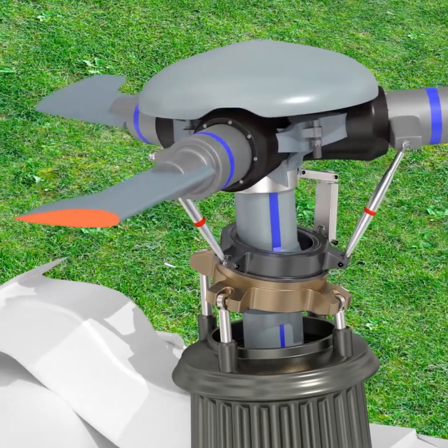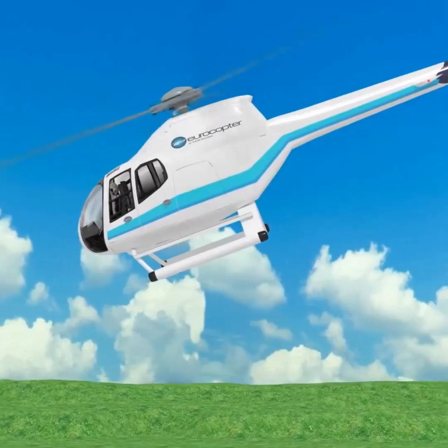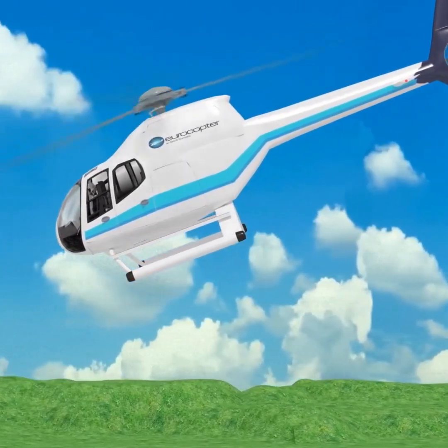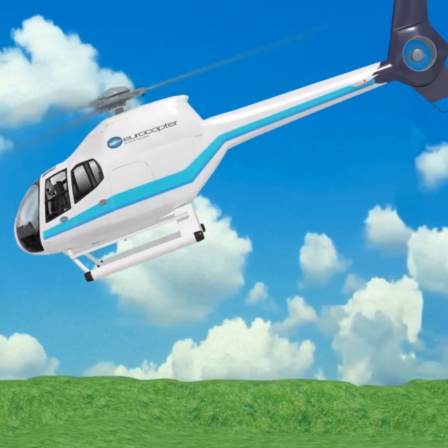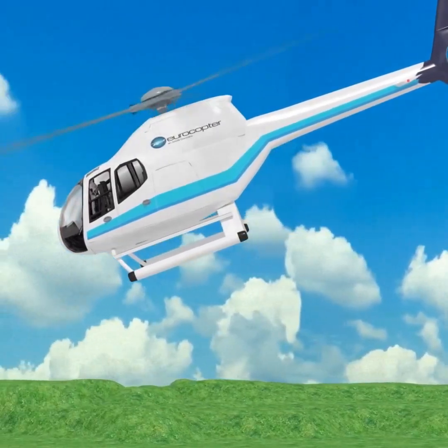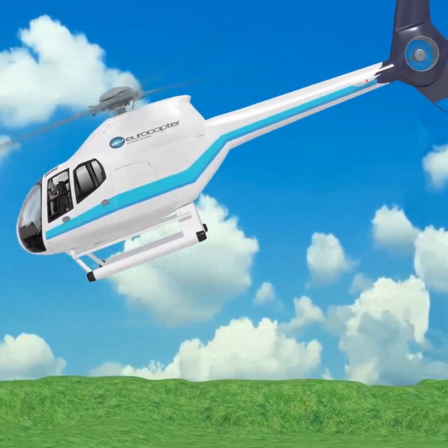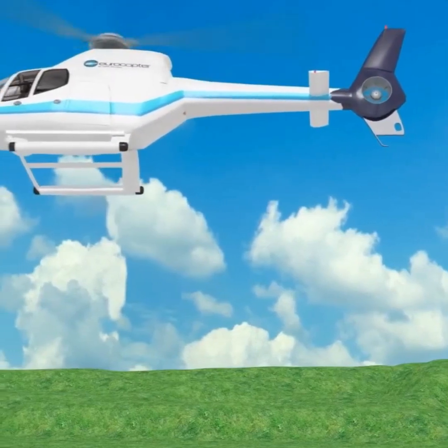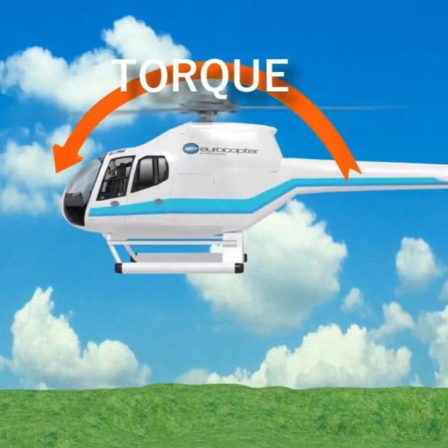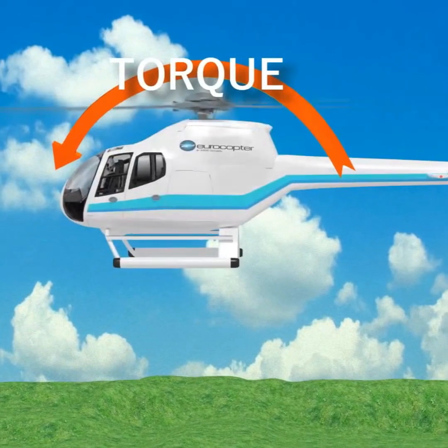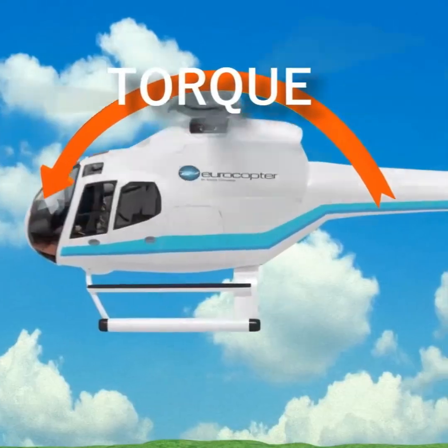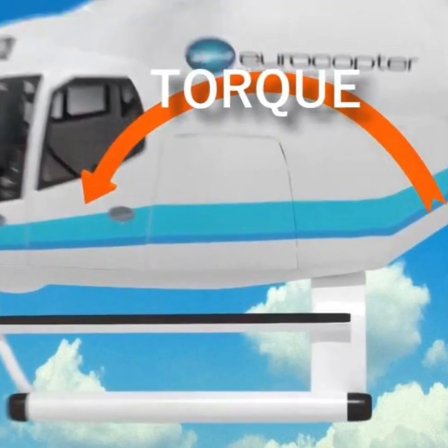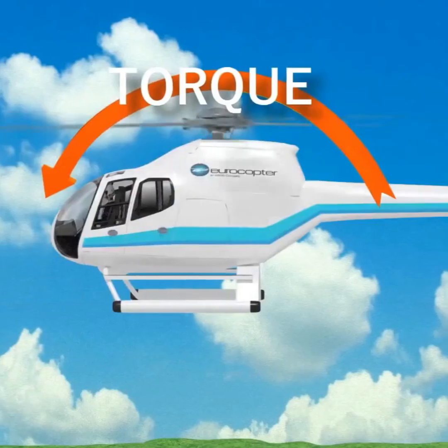Now, let's return to the basic helicopter control. How does this torque affect the helicopter's movement? One might think that the helicopter will tilt forward and move forward. Unfortunately, this answer is completely incorrect. In reality, the helicopter will tilt sideways. As shown, this is definitely a strange effect. To rotate something, torque is applied in one direction and it starts rotating in another direction. This effect is called gyroscopic precession.